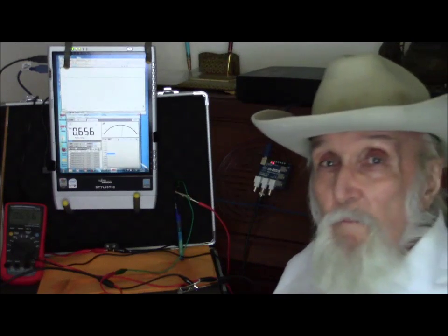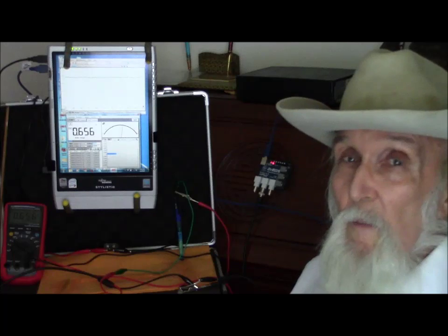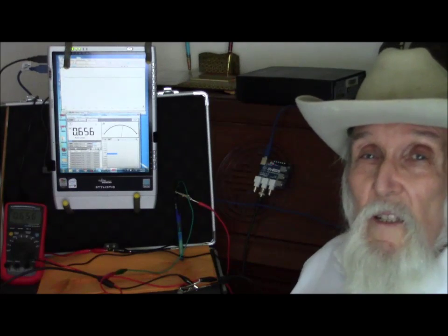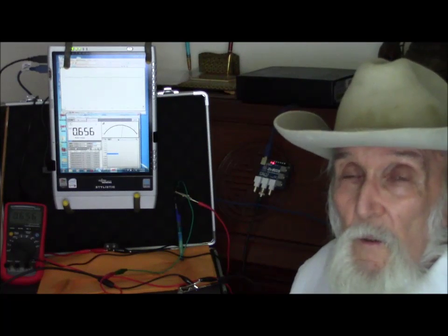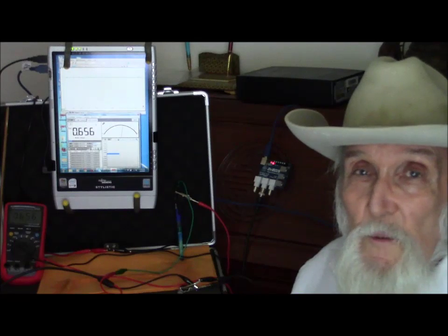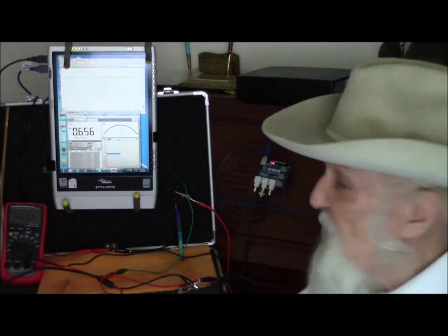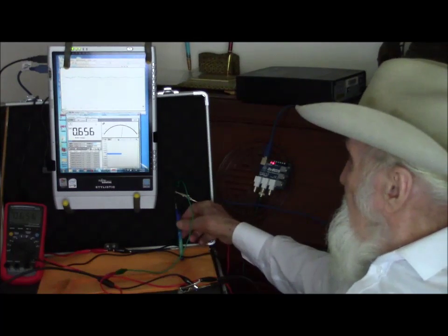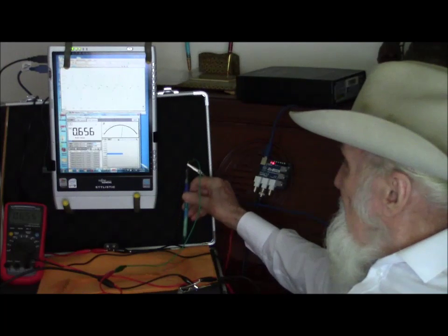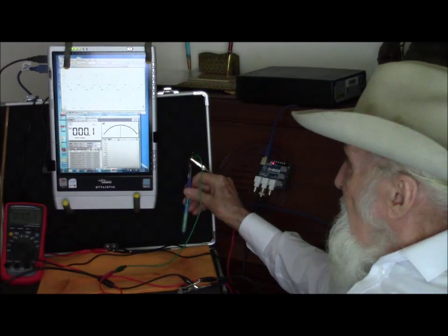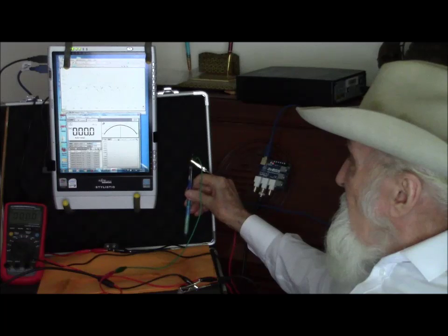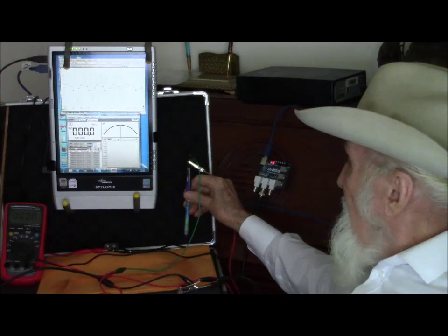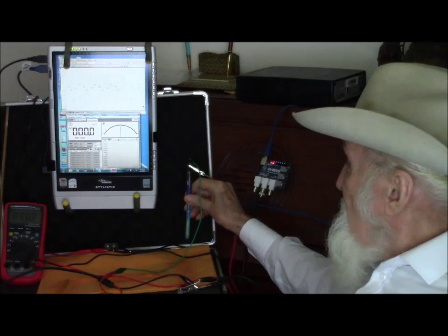This has been known as pipe to soil potential measurements, and of course the measurement is not a potential, it is a potential difference, it is a voltage. You will see that when I lift this, it breaks the measuring circuit and the voltage goes down to zero.